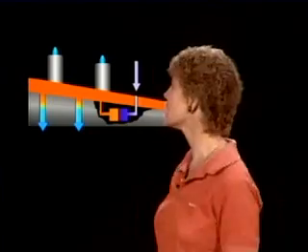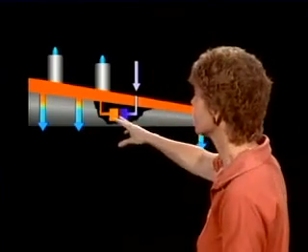The operation of a combustion heater in an aircraft is controlled by a thermostat circuit which basically turns the fuel on and off, and that's a process known as cycling. So basically the way that the combustion heater is controlled is the thermostat simply turns the fuel on and off. It cycles the heater in order to get and keep the air however hot you've asked for it to be.